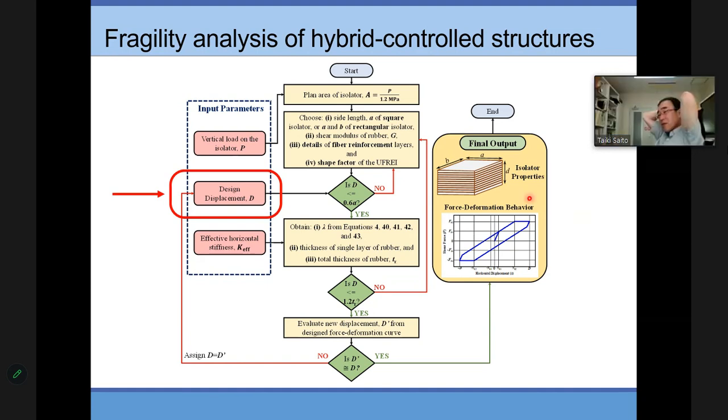I think it's better than fragility analysis. For the fragility analysis, I don't know how to say, it also depends on the earthquake you select. IDA, incremental dynamic analysis, you must do many calculations under many sample earthquakes. But still there is uncertainty about the selection of earthquakes, and I don't know how to check the accuracy of the result or how to use it for design purposes.